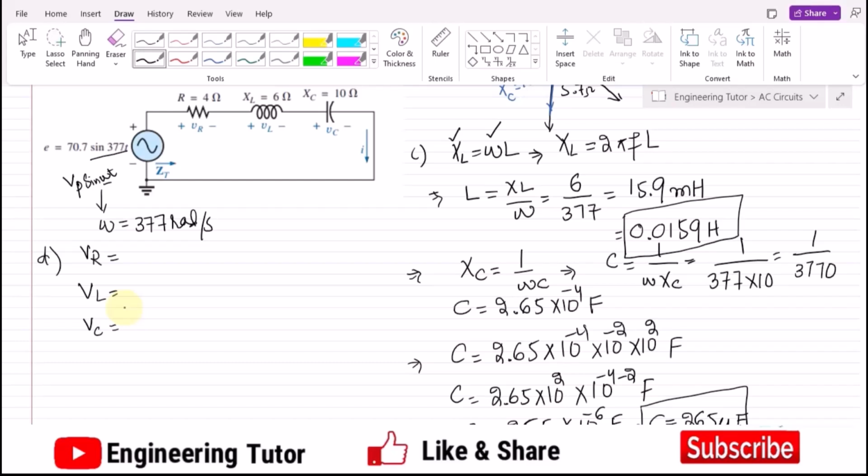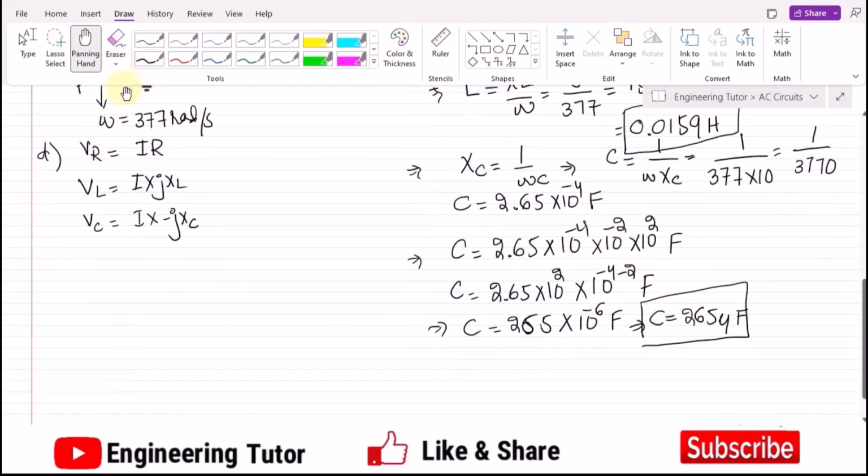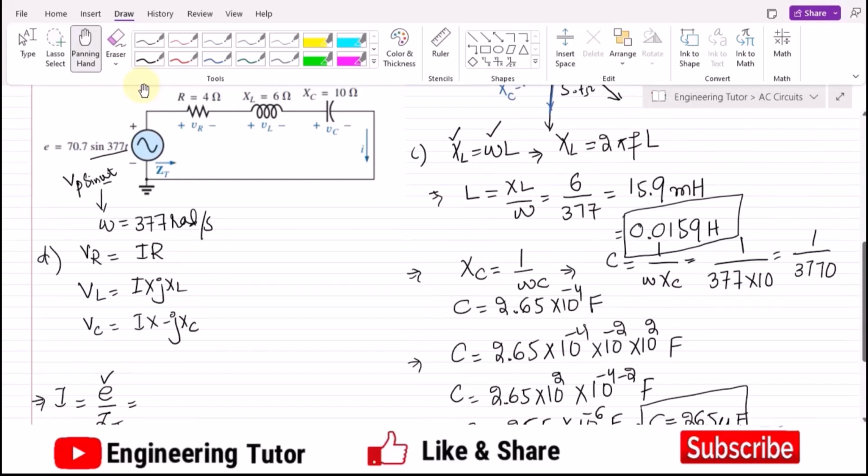So initially, we know that this should be I R, this should be I into j X L, or it would be I into minus j X C. But we don't know the value of I. So first of all, we have to find the value of I. Total current will be equal to the voltage divided by the total impedance. But here we don't know the value of E. We have just the expression of E, but we don't know the values in the phasor form, because now this one is the peak value.